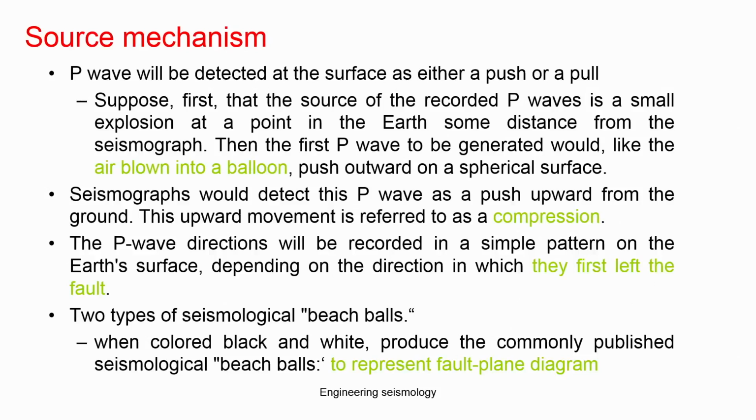So, in today's class we will be seeing a simple simulation of ground motion, theoretical models and source mechanism. What do we mean by the source mechanism? The source mechanism basically describes what type of fault it is and what type of force is radiated from the earthquake source or released by the earthquake. It is predominantly described as a compression or tension force.